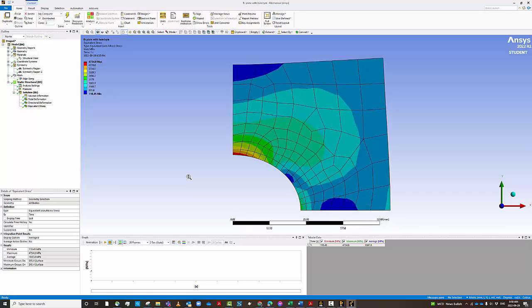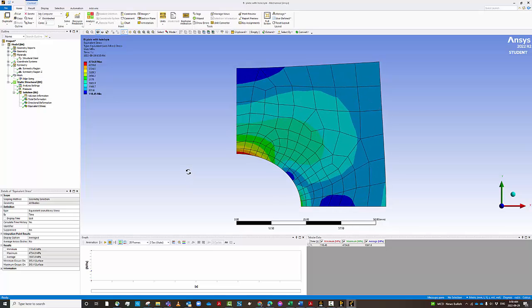So the purpose of this exercise was to show you some of the mesh control, show you the rigid body motion, and show you the use of symmetry. Of course, we didn't have to use the symmetry for both. You can decide, for example, I want only to create half of it and use symmetry about only one axis.